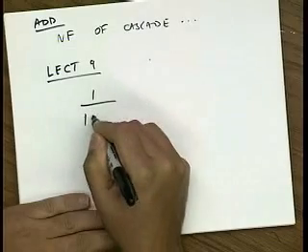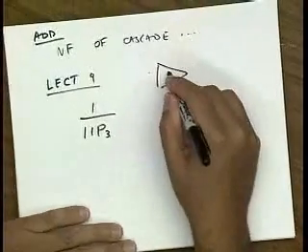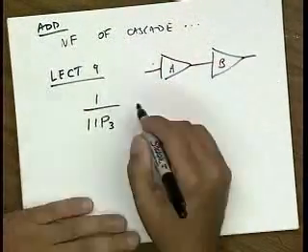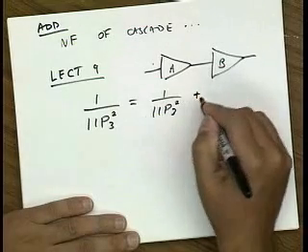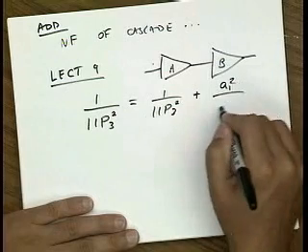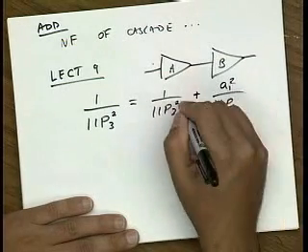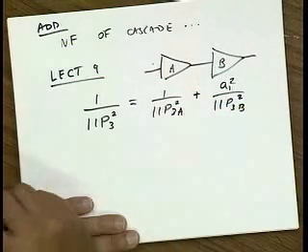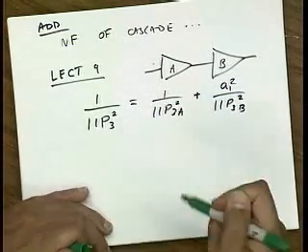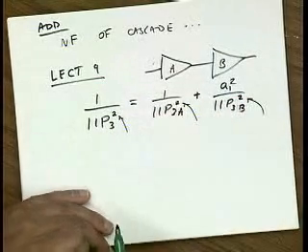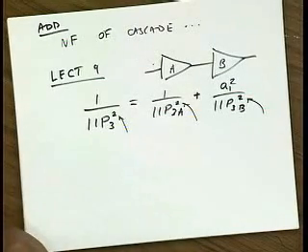All right, another announcement. I think the notes are already updated online, but on lecture 9, I made a mistake in the derivation. In lecture 9, we derived the input IP3 of a cascade. We have two blocks, A and B. When we did the derivation, we forgot to take the square root. And so, consequently, the right equation is as follows. So this should be squared. So this is A, and this is B. These are all in terms of voltages. If you go back and look at the notes, you'll notice that the squares now appear. Okay? So thanks to Kevin for pointing that out.